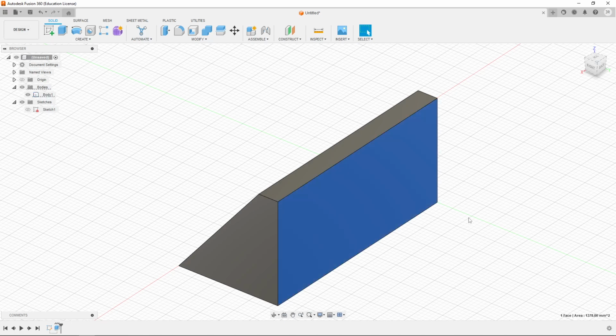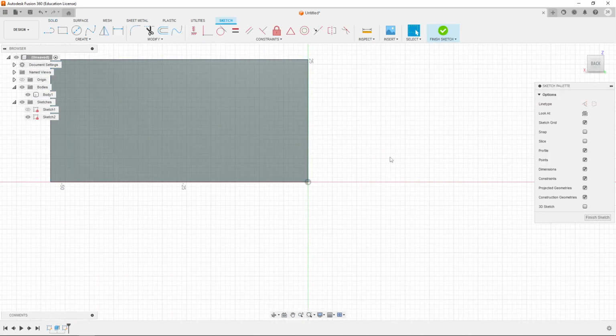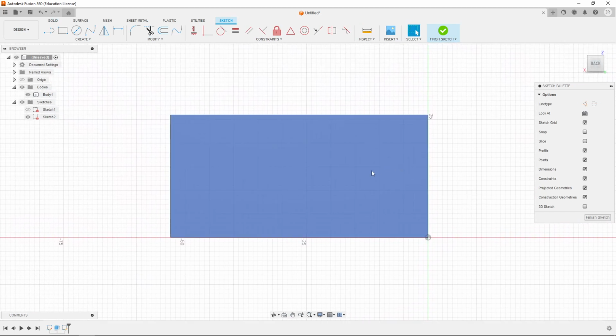So before I click new sketch, I'm going to click on this face, and notice how it turns blue. And so it says, okay, when you click the sketch button, it's going to draw the sketch on this face. And you'll see it'll give us a camera perspective immediately. And it won't even ask me what plane we're on. It knows the plane is, in fact, this face. So here we are, create sketch. Notice it rotated it. Now I have to move my view a bit by panning so it's nice in the middle. And here I am in a new sketch.